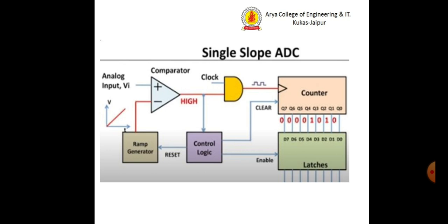This process will keep on repeating till the analog input is greater than the applied ramp, and the counter will keep on counting.